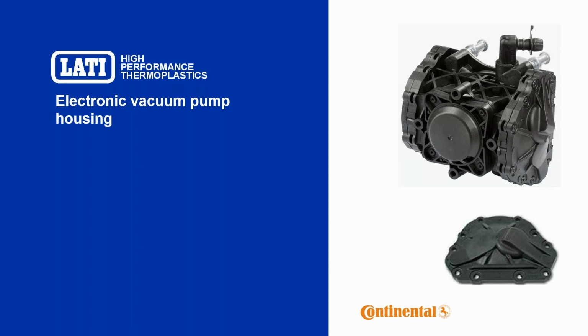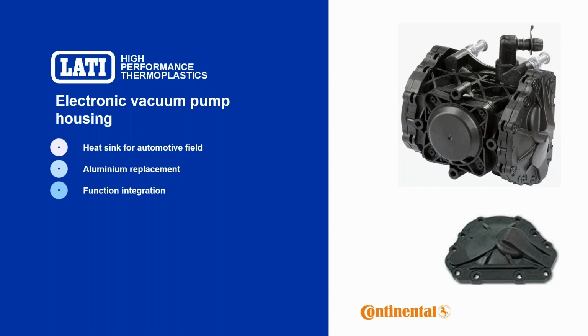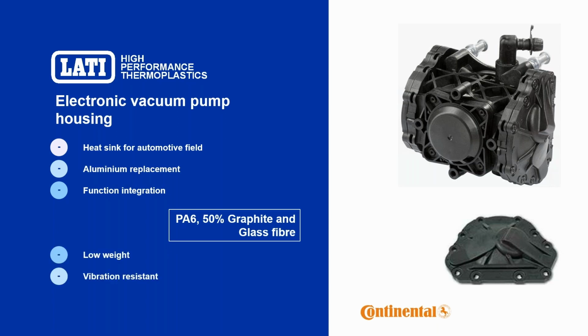Now we move to a case history from a different sector compared to LED lighting, and this component is in the automotive field. It's an electronic vacuum pump housing. It's an aluminum replacement, and we selected a polyamide 6 featuring both graphite and glass fiber. This way it was possible both to dissipate heat, but also to have a component which is resistant to the vibration which is typical of the automotive field.